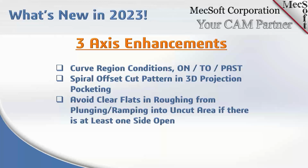We also added another cut pattern in 3-axis projection pocketing for the pro users. You can now do a spiral offset cut pattern that is projected down onto the part. And then we have made horizontal roughing more robust in this release. We eliminated the possibility of beginning your plunge motion in an area that's not been cut yet, which is not a good thing to do. So we handle this a lot better in this release. We'll be showing you that.